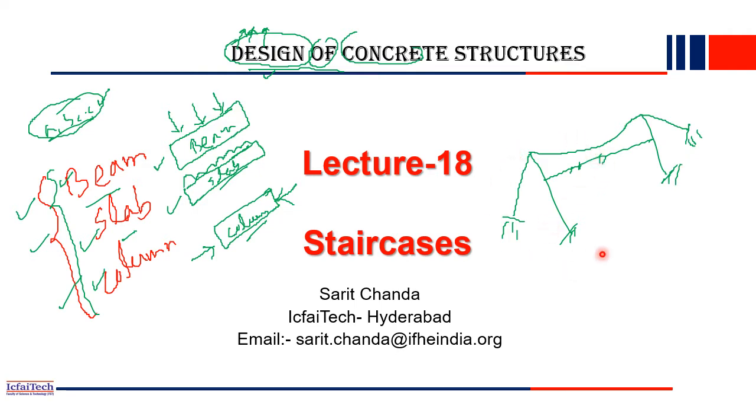Like that, any structure in the world can be divided into a beam, slab or column, depending on how the loads are acting and what the shape of the member is. Based on these criteria, you can divide it into any of these three and then design it. Beam design we know individually, slab design we know individually, and column design also. If you know the basic element design of RCC structures, then we can design any structure. We simply have to decompose the structure into these three elements and design the individual members.